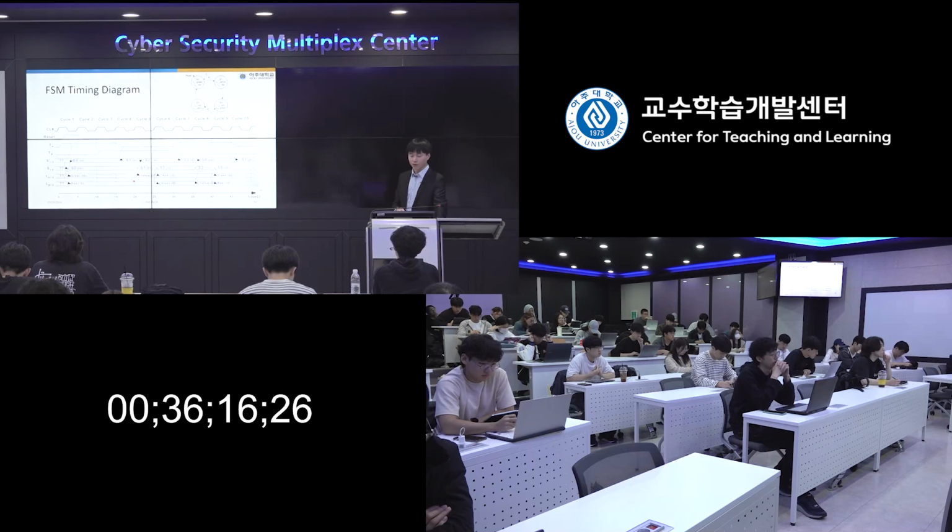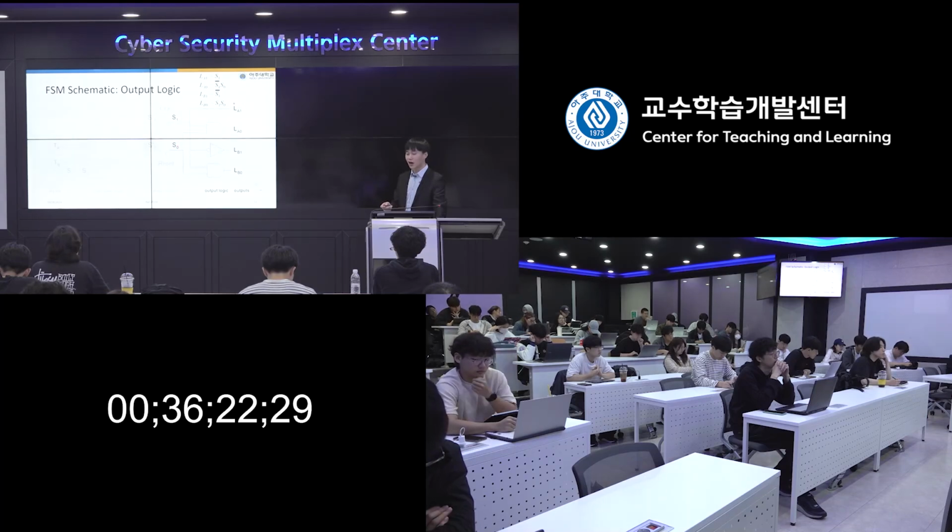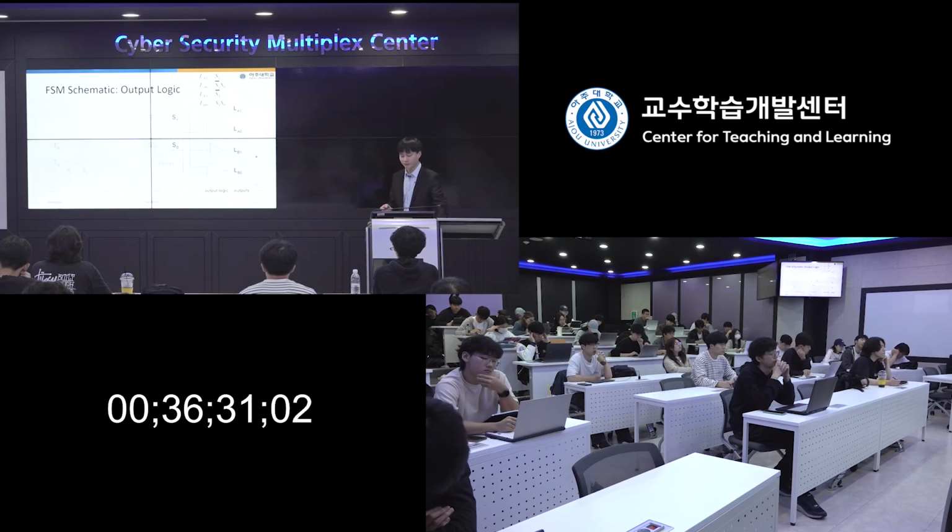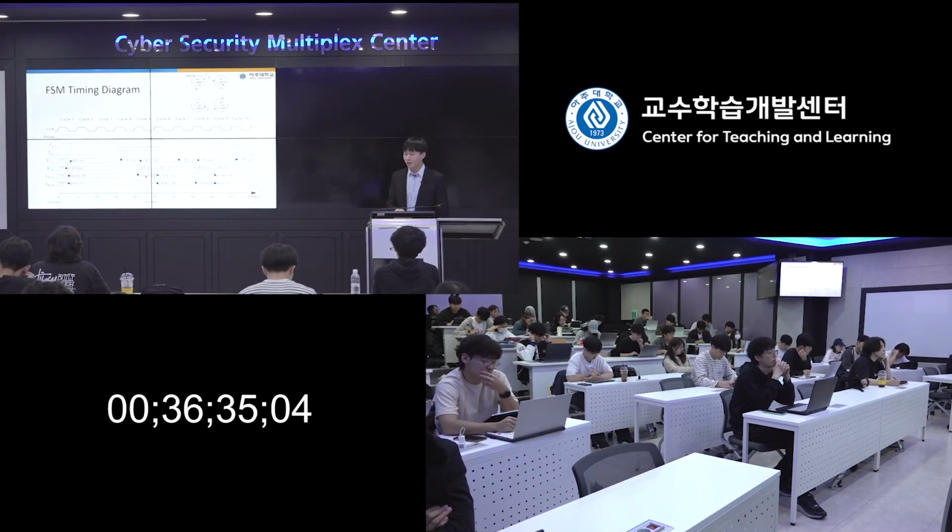The output checks the output logic. You will immediately check S0, S1, then update the control logic. In this case, it will update LA to be yellow. LB is still red, did not change.